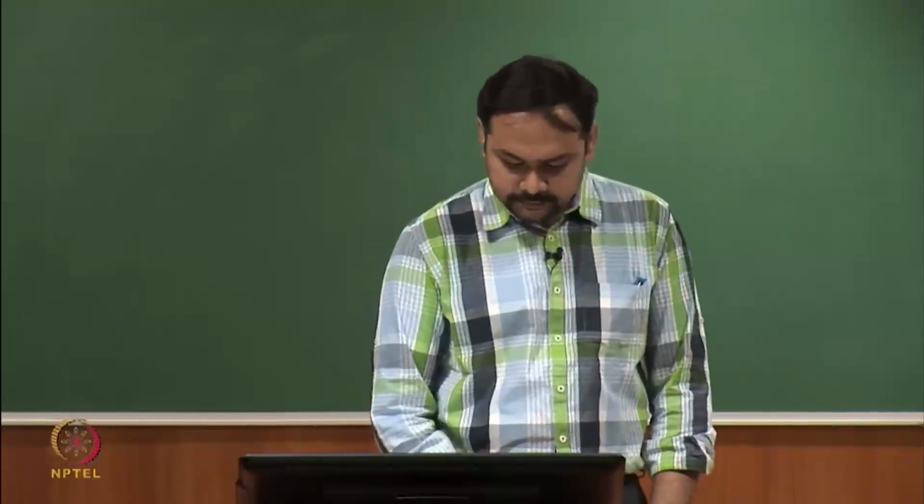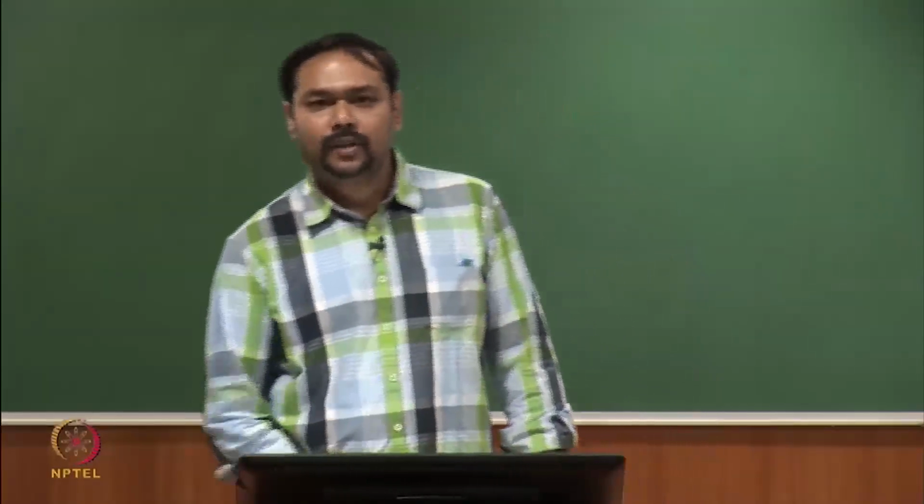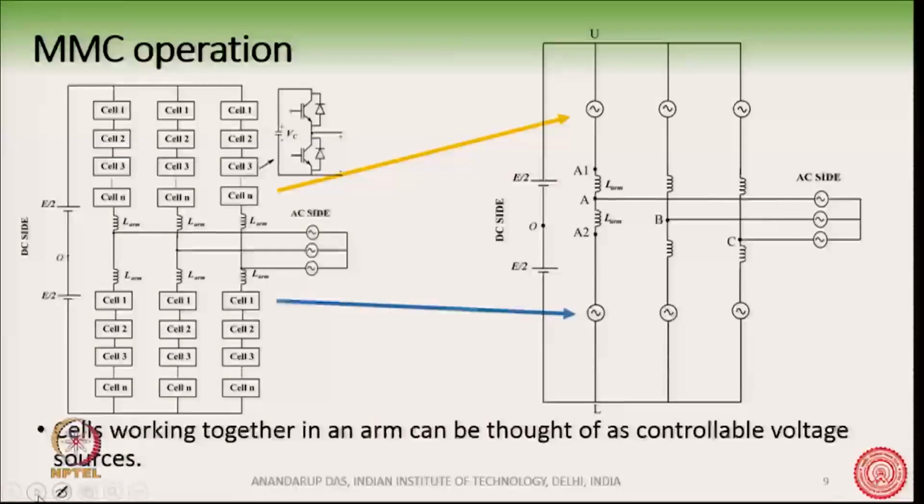So, with this understanding of the arm voltages, let us analyze the converter. Suppose we take again the simpler case, the half bridge variant. Let us start with the half bridge and see how the MMC circuit can be modeled. You see all these cells, as I told you, when all these cells are connected, they